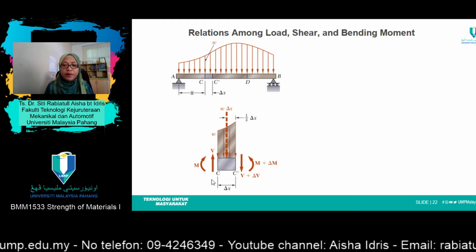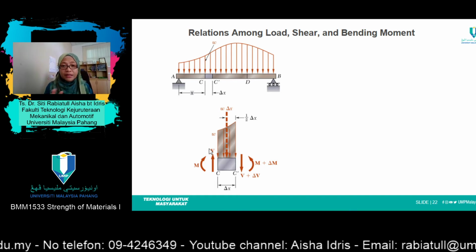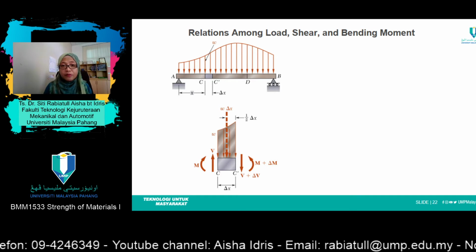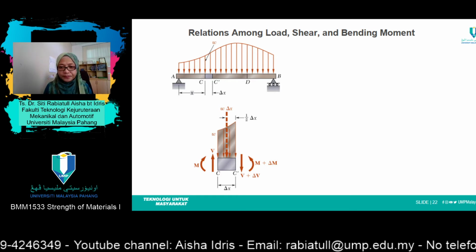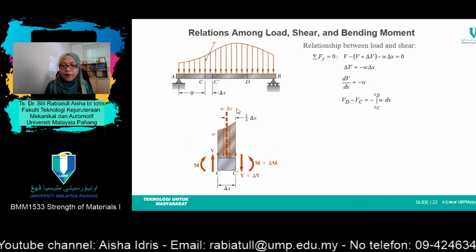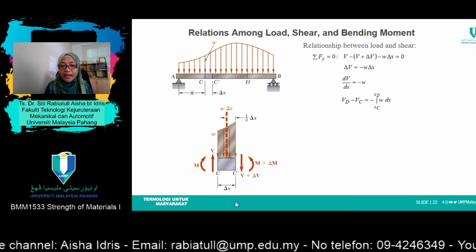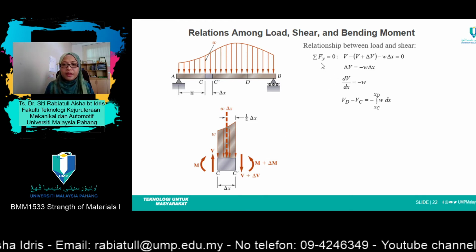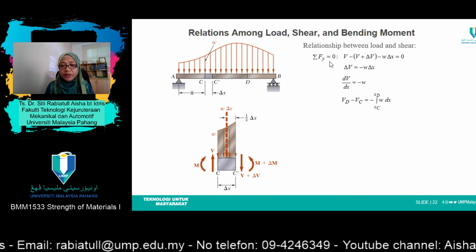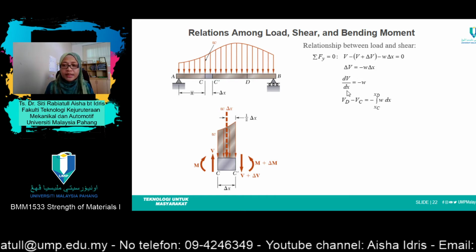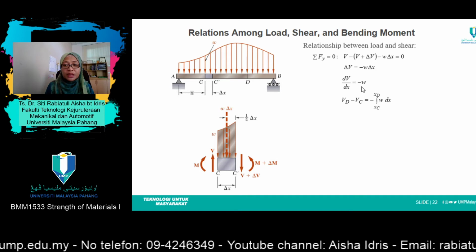Remember, different direction of cutting will have different sign convention for internal shear force and also bending moment. So from this cut section, you need to find the total forces in y direction. From there, you'll get this equation, which is dV over dx equals negative w.